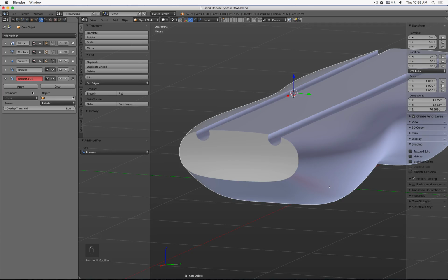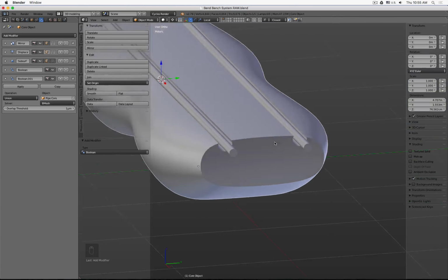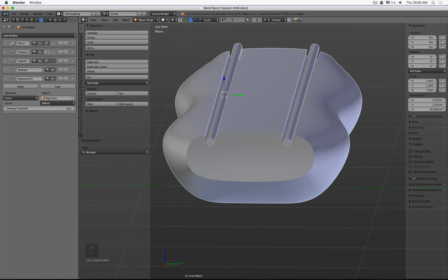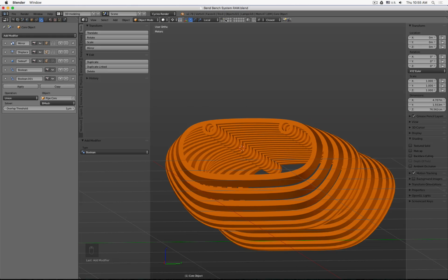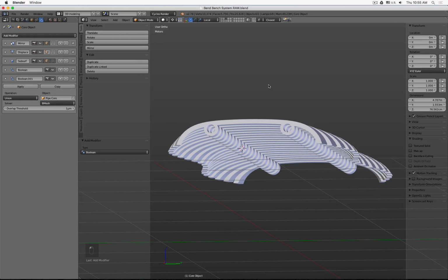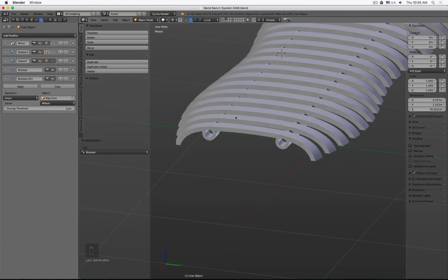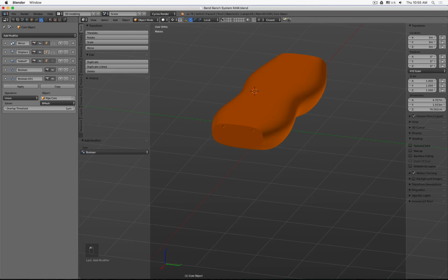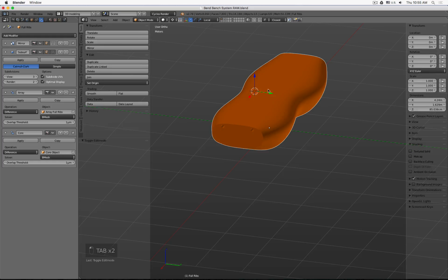This time we say union and pipe core. See, we just added actually to this volume, and if I'm not mistaken, there we are. So you see it cuts actually both objects at once. So I saved myself the step of adding to each object another Boolean operation.